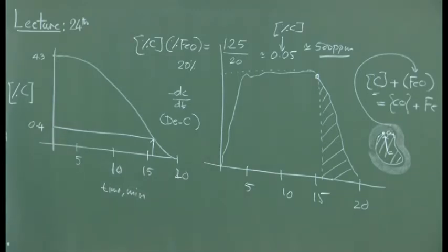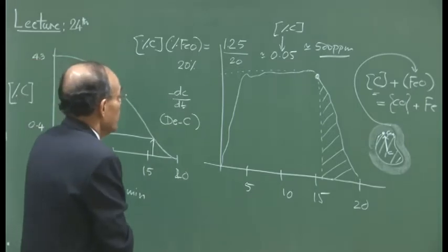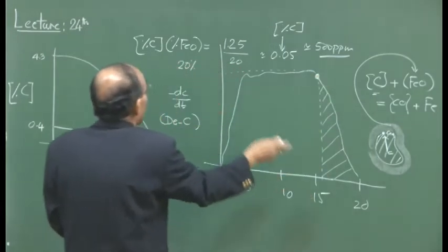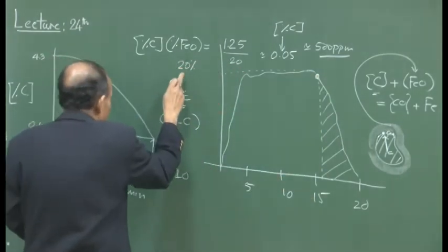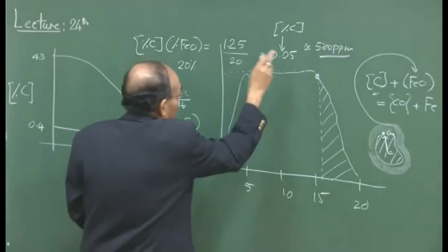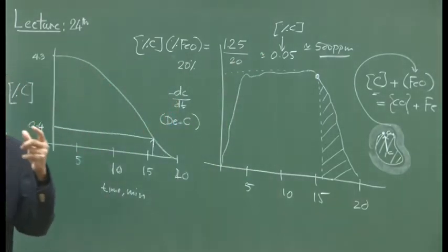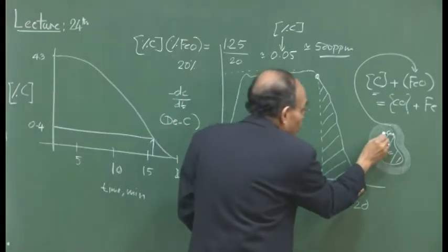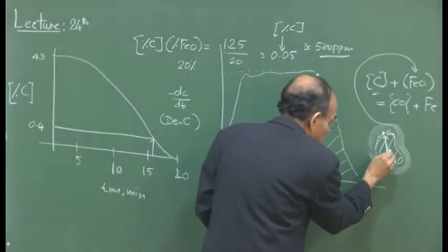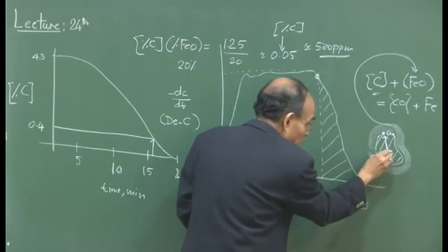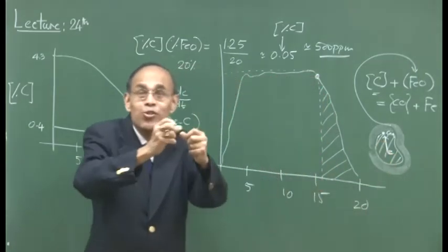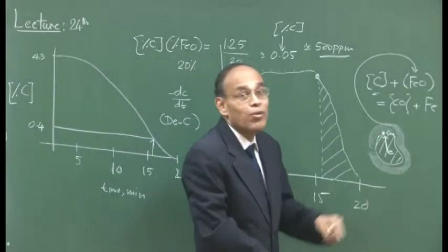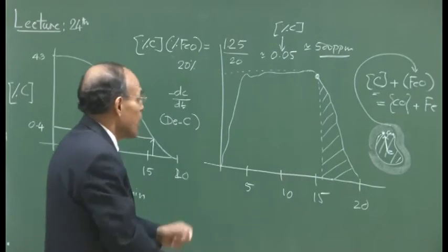So, if there is a slag metal equilibrium, eventually you will see 500 ppm oxygen dissolved in the metal, you will see 20% weight percentage of FeO in the slag, and correspondingly you will see about 500 ppm carbon. So, that is your equilibrium carbon content, and this equilibrium carbon content minus, sorry, the bulk concentration, which is higher than the equilibrium concentration, because carbon is continuously being consumed at the surface. So, C minus C equilibrium represents the driving force for carbon to diffuse.